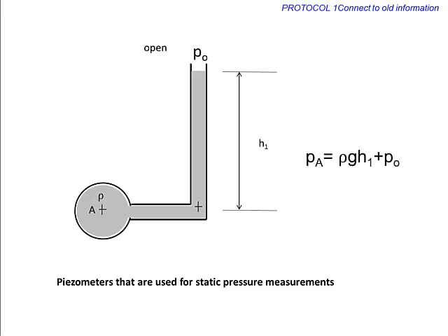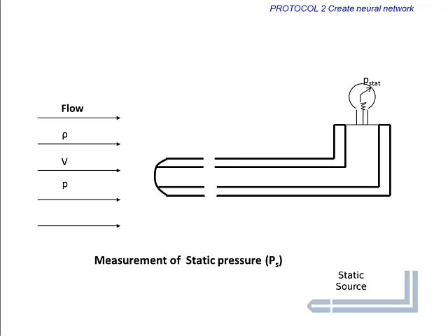To measure static pressure at a given location inside a flowing fluid, a static pressure probe as shown in the figure can be used. It is a tube with holes exposed to the flowing fluid as shown in the figure. Connecting this tube to a manometer or mechanical gauge, the static pressure can be measured. Note that a static probe doesn't have an opening at the front end of the probe facing the flow.